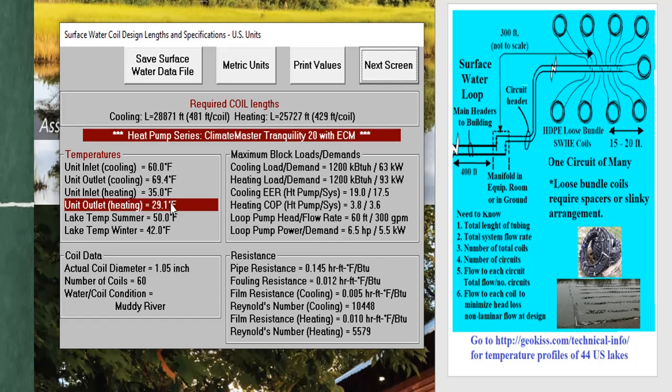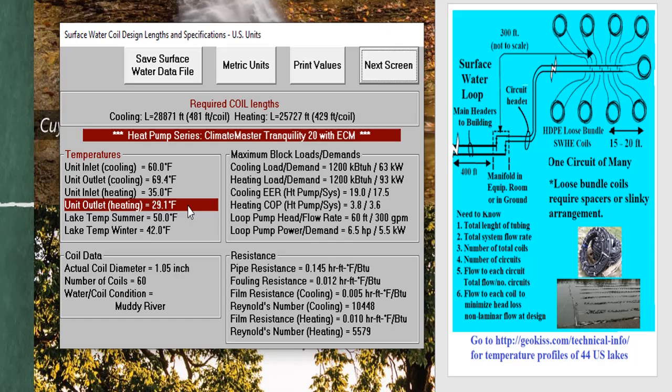It's flashing there because it's freezing, or it's below what normally happens when a heat pump shuts off without antifreeze protection or freeze protection. And so this one is in pretty good shape. We should be able to expect the 15% propylene glycol would be plenty of material. Okay. Now some other things we can see. This particular machine is cooling. It's doing great. It's really doing good.